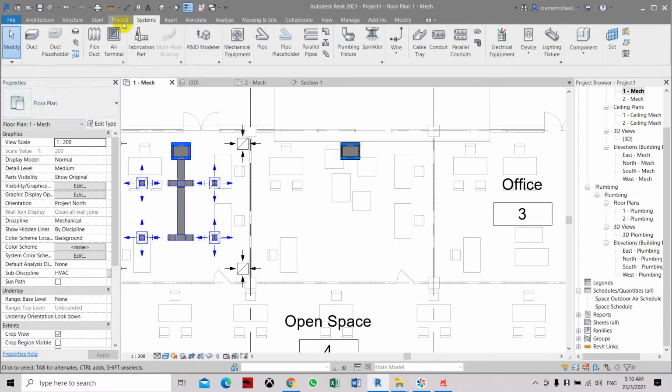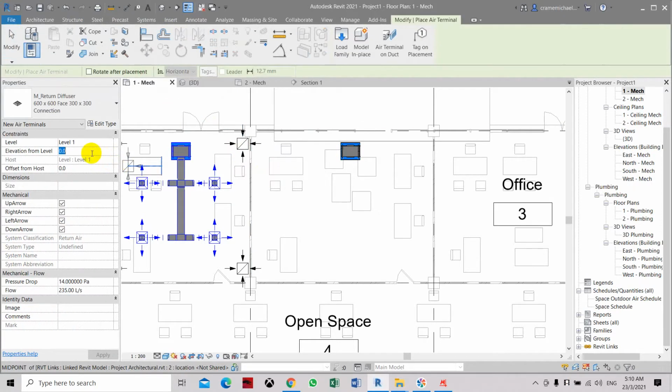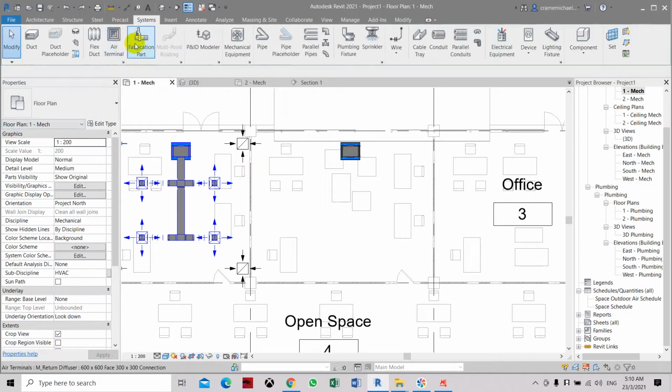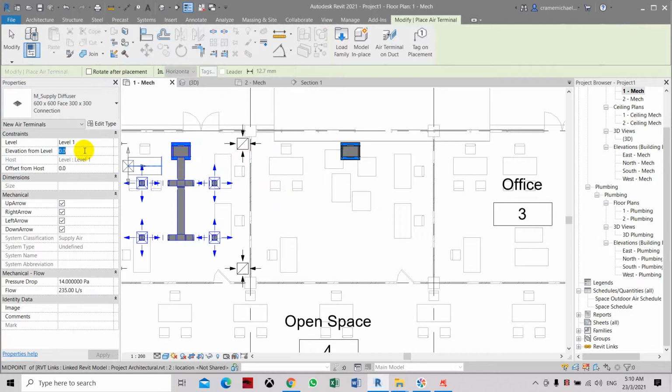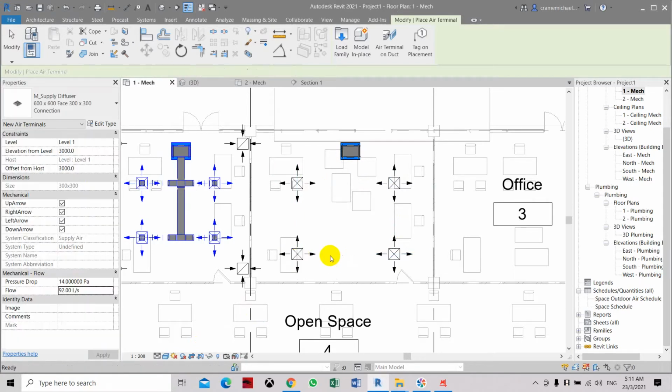Here we're going to also place the air terminal, again 3 meters. Okay, it's not this supply, so let's undo the terminal, set it as a 3 meters height from floor level, and the supply will be 90, so it will be the same as the previous layout. Here we're going to place the location. What we're going to do is I'm going to show you how to use the ductulator online to size this ductwork.